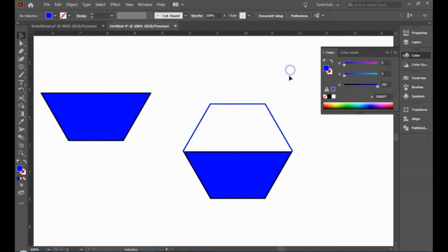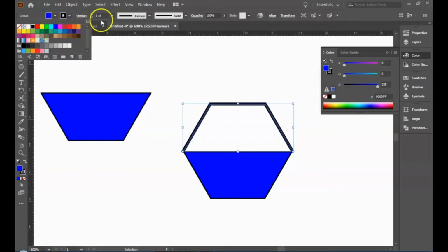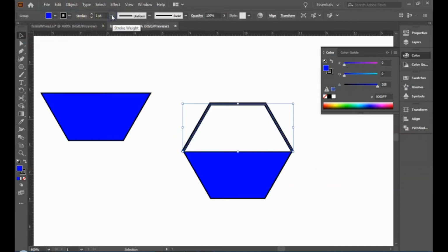But now, if you do that, you cannot see the stroke anymore. Alright, so now you can change the stroke. Okay, give a color to your stroke and change it to, if we make it 0.5, you couldn't see the fill because it's too thick. So make it 0.25. Don't worry about that because this one, the width of your stroke is still 0.5. This one is just the stroke of your stroke. You get it? I hope.